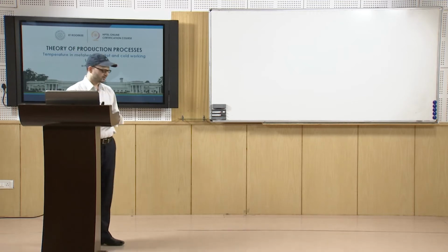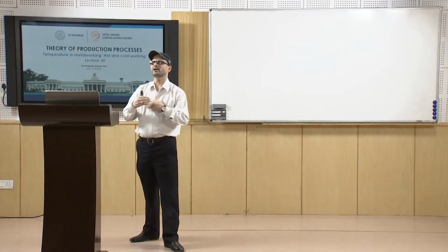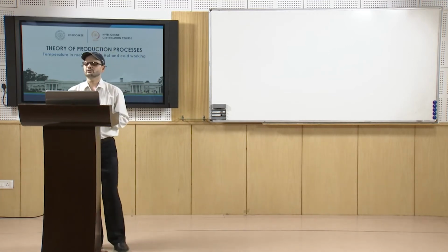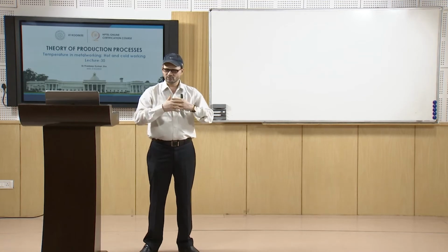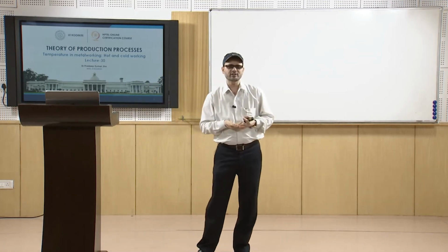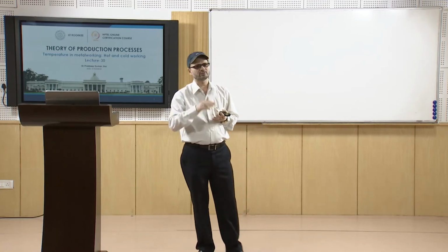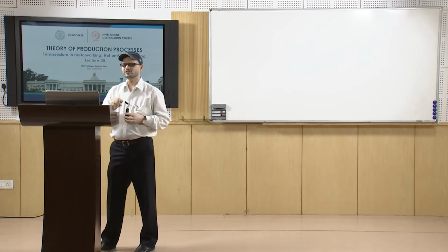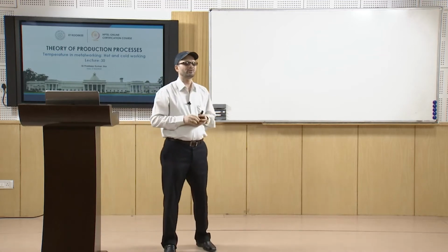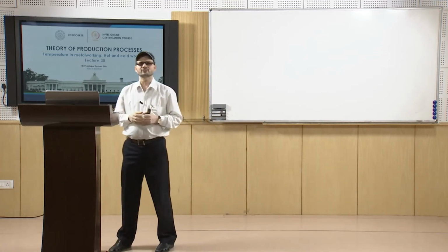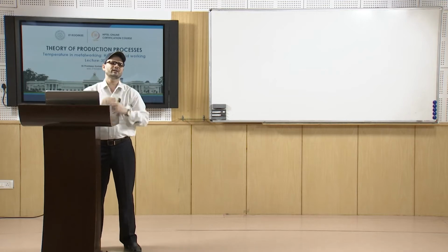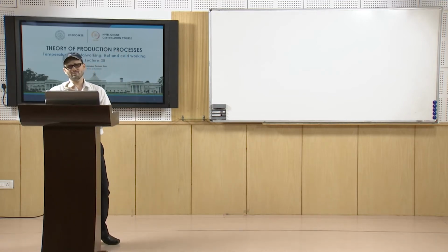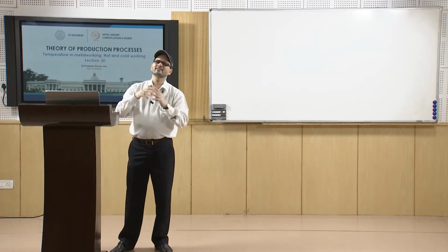Second, a trait of this hot working process is that you can allow for large deformations. Because the recovery process is active, you do not have the condition where the flow stress is increasing with time. So, flow stress is normally constant, which is the third point: it occurs generally at constant flow stress. Because of this constant flow stress value and the higher temperature, you can go for a larger degree of reduction. So, large deformation is possible, and flow stress is normally constant because we are working at a higher temperature.